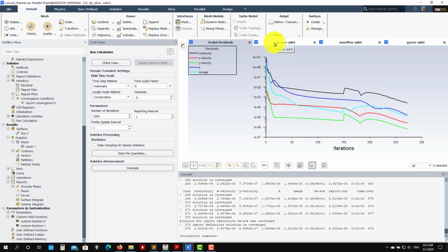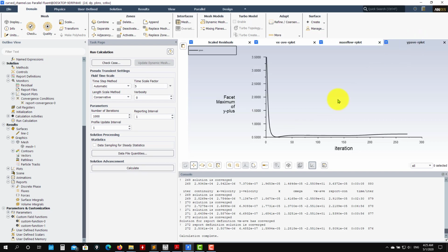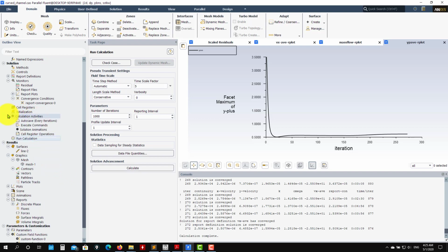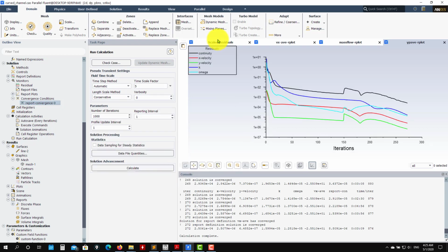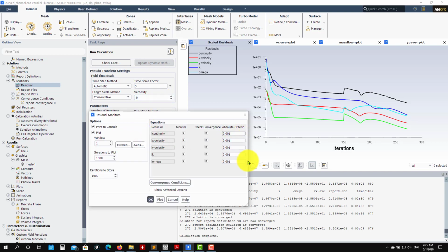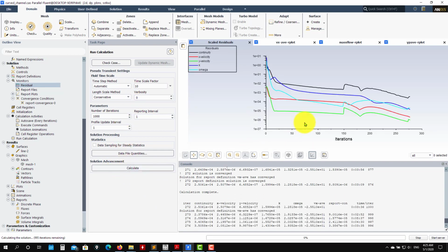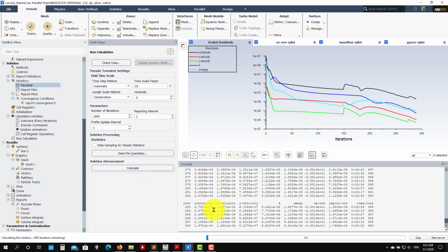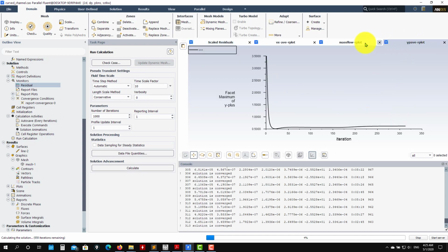However, I still see that the quantities are still oscillating a little bit, so I think it might be better to reduce the residuals. Let me put 0.4, and before that let me increase it to 10. I know with 10 it will still work, and see, boom boom boom boom, it should be converging now. Then it's measuring the other quantity.